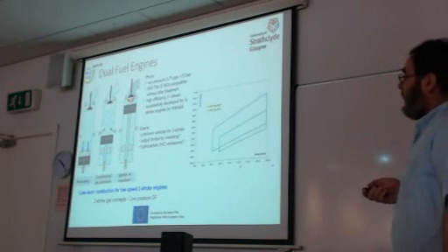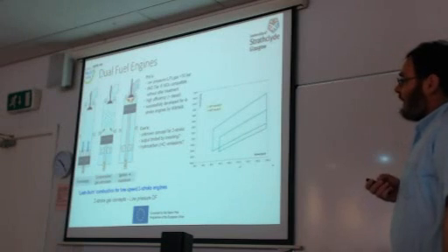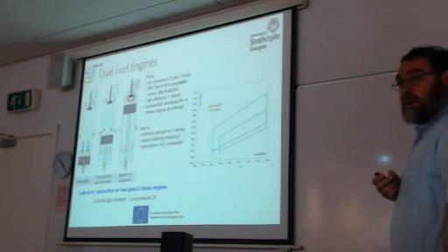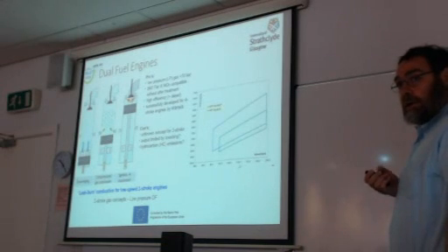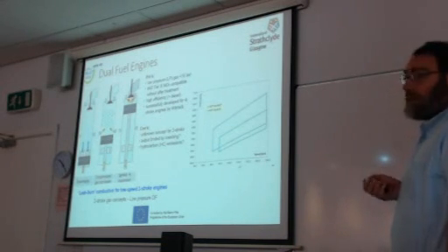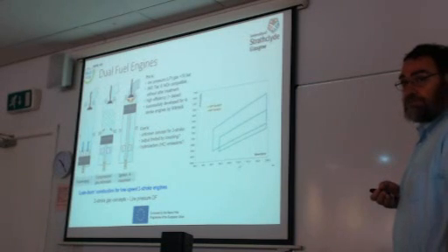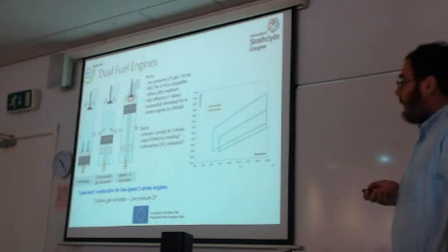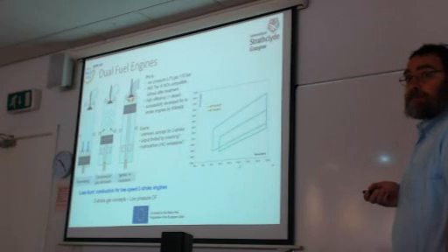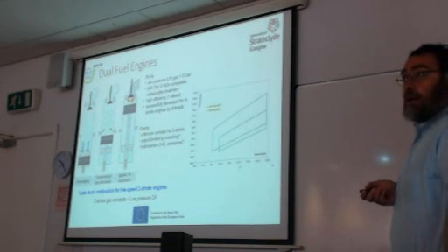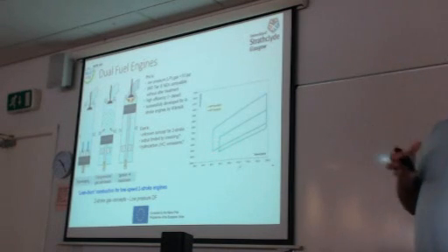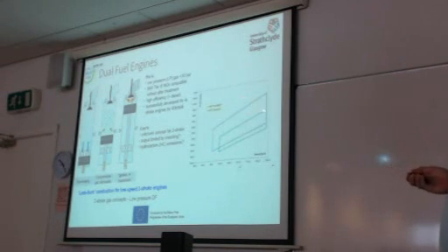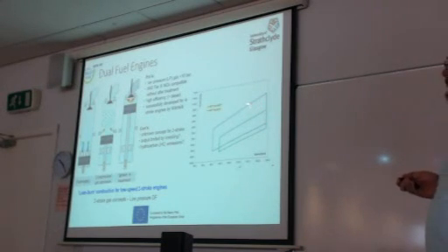Which is the advantage? We discussed the advantages and disadvantages of premixed combustion. Certainly we expect low NOx, and of course this type of engine complies with Tier 3. But which is the disadvantage we expect from this concept? Take into account that this engine needs to operate at lower pressure levels. Higher carbon.